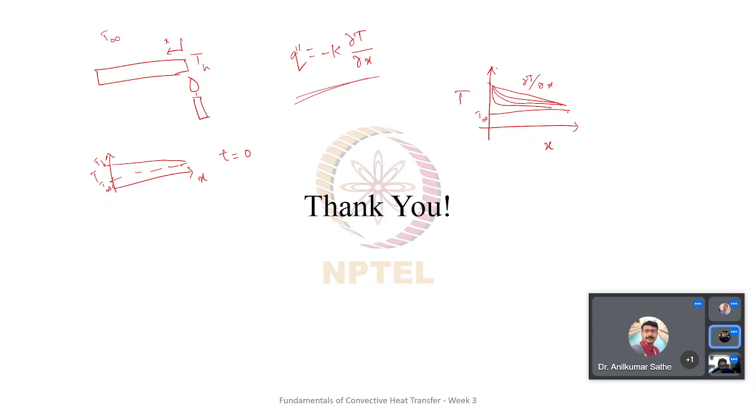Am I audible? Yeah. Sir, actually in Fourier's law, there is one assumption that constant thermal conductivity. So the constant thermal conductivity with respect to what? That means it's respect to time or it's respect to space? Both. This K, the thermal conductivity, is neither a function of x nor a function of time. K is a constant.